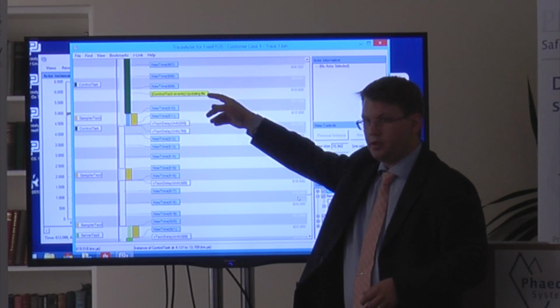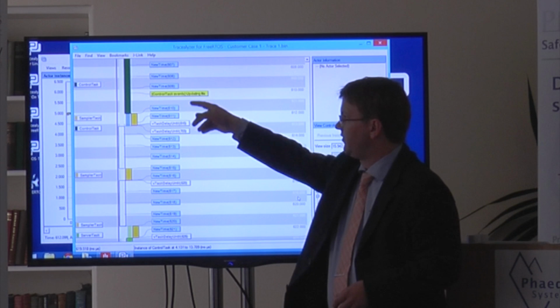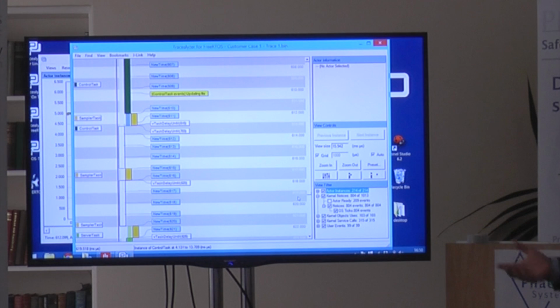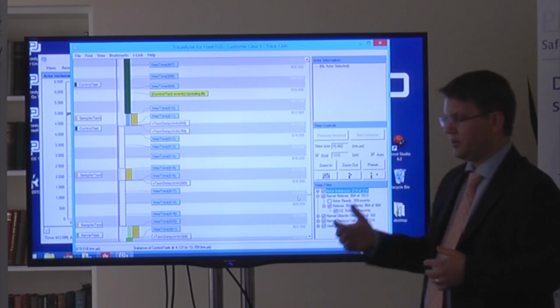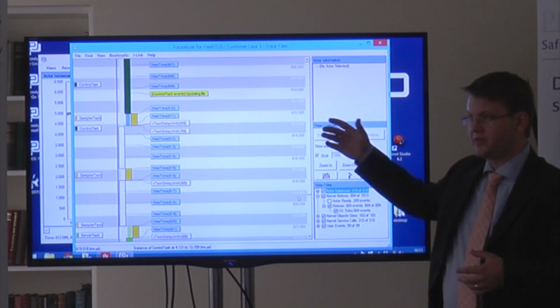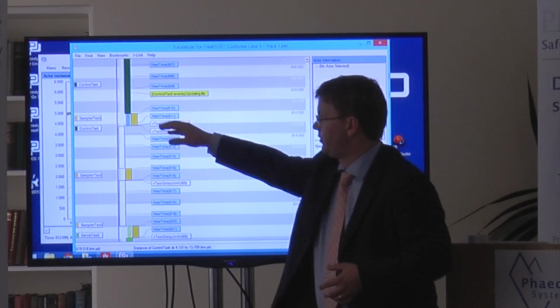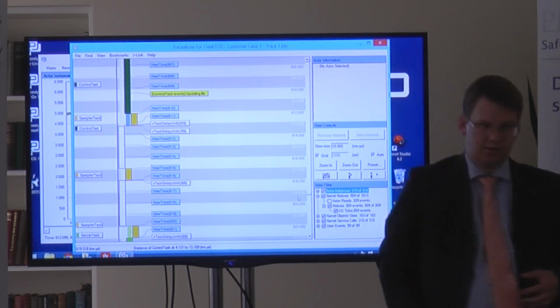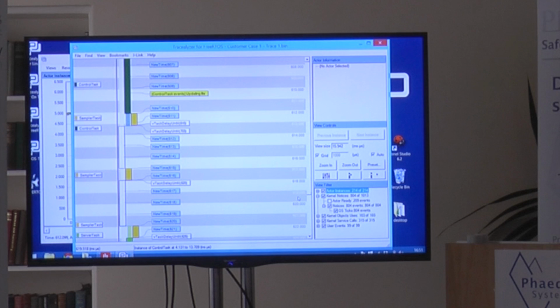If we add more information here, things that have been recorded, we see this logging thing that it's updating some file at that point. And so it's probably some sort of critical section related to the file system. And when they looked further, they realized that they were actually disabling interrupts to implement this critical section. And this interrupt disabling, it worked, but it also disabled the scheduling. So therefore this task was delayed, even though it had nothing to do with this particular critical section. So it was kind of a stupid mistake that was discovered this way.